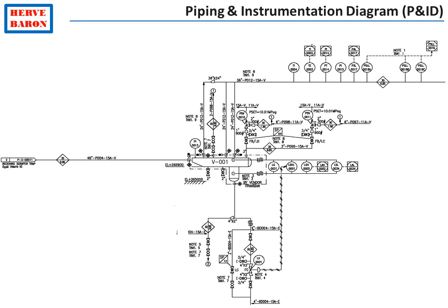All valves are shown, not only control valves as on the process flow diagrams, but manual valves as well. All instruments are shown, not only process control instruments, but also instruments used for monitoring, as well as alarm and process shutdown.